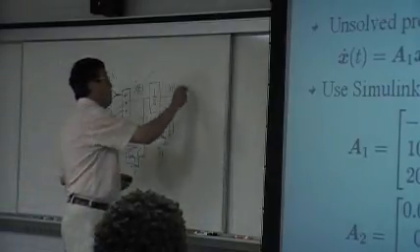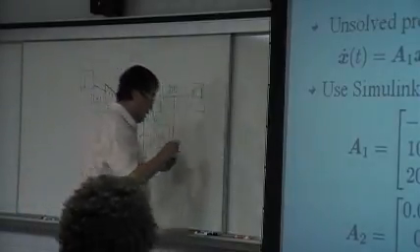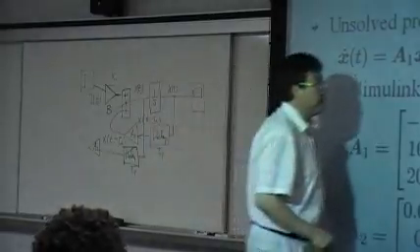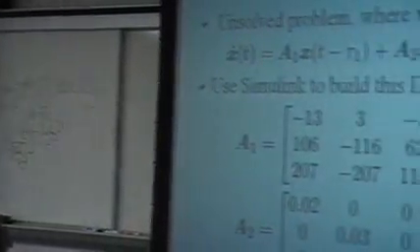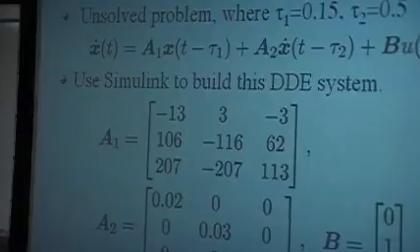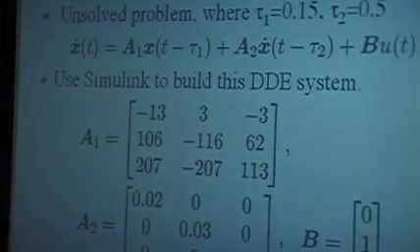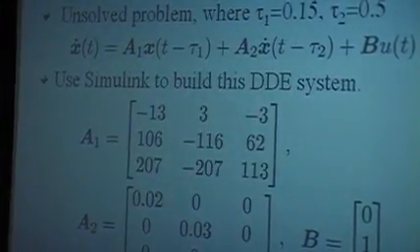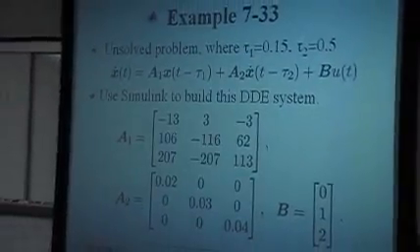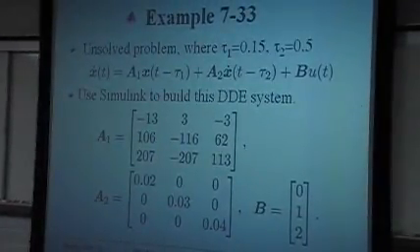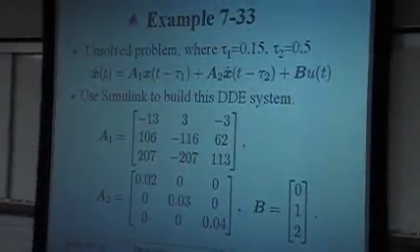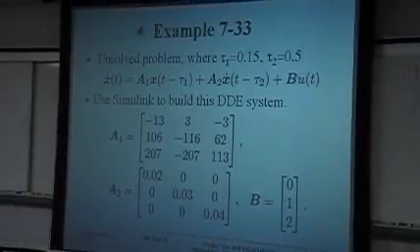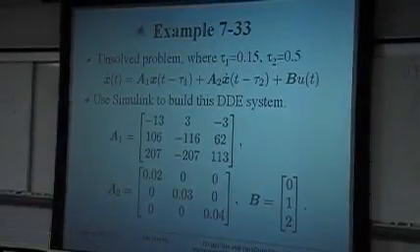We can then make a code. So for this kind of system, we cannot easily solve it with the Matlab command DDE23, because it cannot handle neutral type delay differential equations. What we can do only is to create a simulation block diagram.